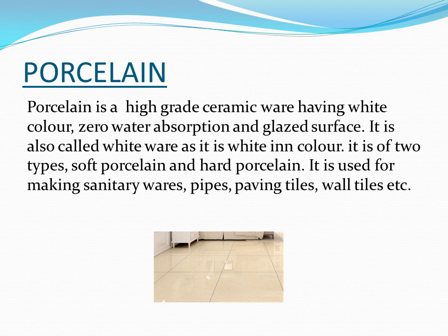Fire clays are finely dispersed earths consisting of kaolinite with quartz, feldspar, hydromica, and carbonates. They are mostly used to fabricate wall and insulating fire bricks, which are used in masonry and furnace lining, respectively. That is both in masonry and furnace lining. Fire clays are also used in porcelain, faience, and other ceramic articles.